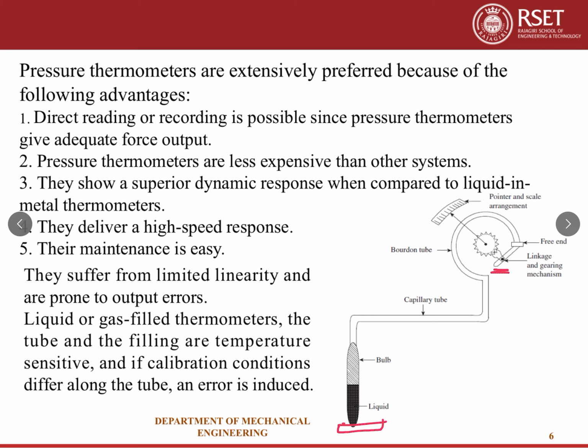So pressure thermometers are extensively preferred because of the following advantages. Direct reading or recording is possible since pressure thermometers give adequate force output. Here we are getting adequate force output, so we can get a direct reading. We are not recording any other conversions. The pressure thermometers are less expensive than other systems. They show a superior dynamic response when compared to liquid in metal thermometers. They deliver high speed response. Their maintenance is easy too.